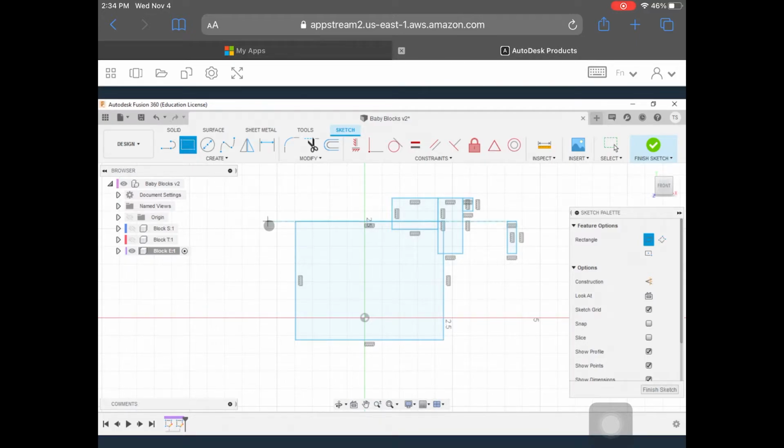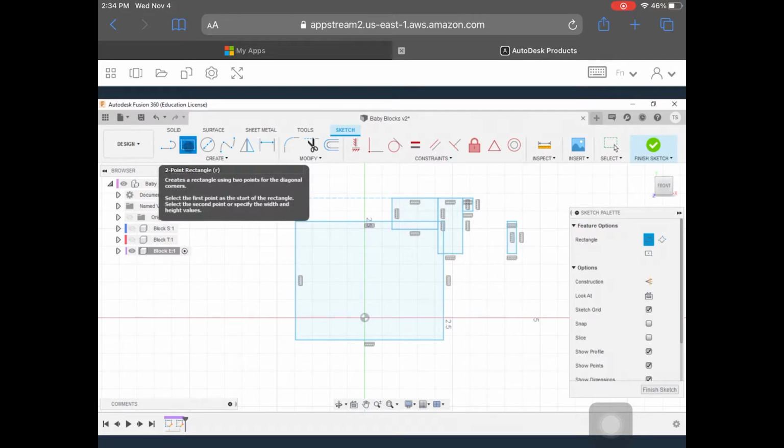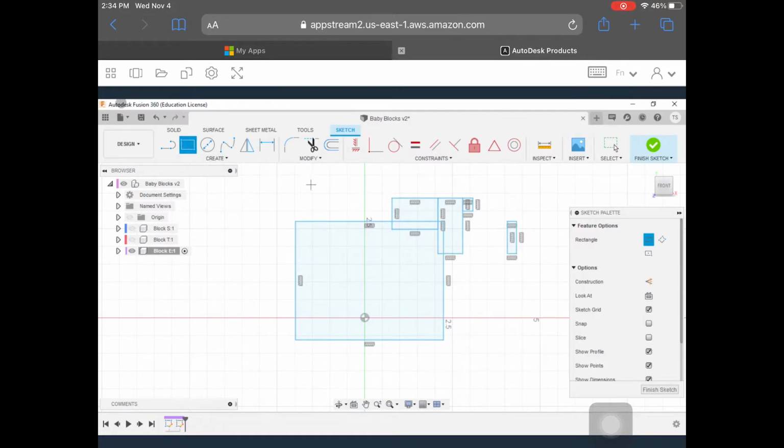If you make a mistake like this, chances are you kept your drawing tool active and you just kept clicking because you didn't know how to exit this drawing tool. So here's how you fix this. Whenever you're done drawing, right click with the right mouse button and then left click cancel. What that does is it deactivates our drawing tool.